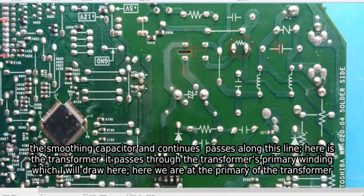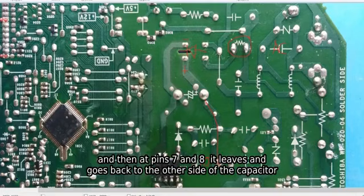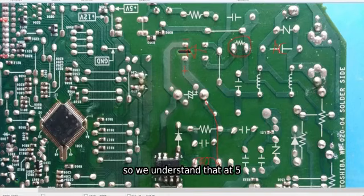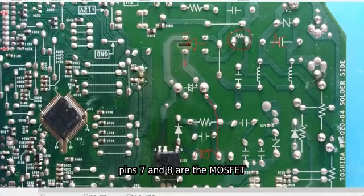Here is the transformer. It passes through the transformer's primary winding, which I will draw here. Here we are at the primary of the transformer. And goes to pin 5 of the integrated circuit. And then at pins 7 and 8, it leaves and goes back to the other side of the capacitor. So we understand that at 5, pins 7 and 8 are the MOSFET.